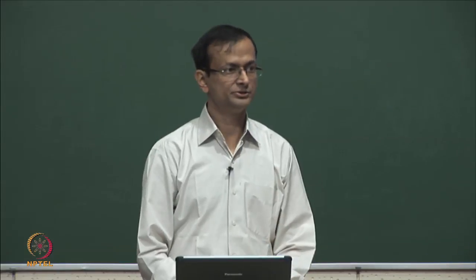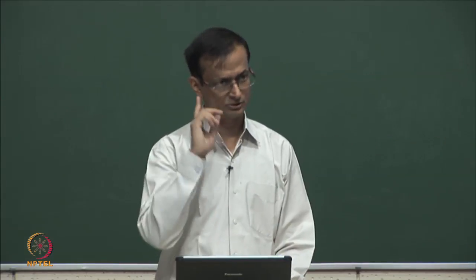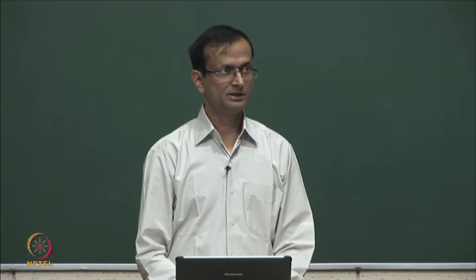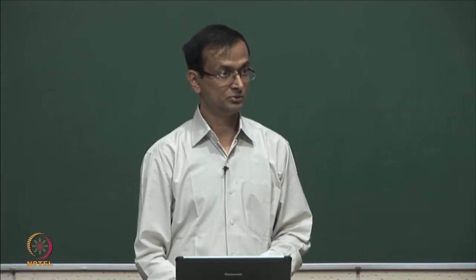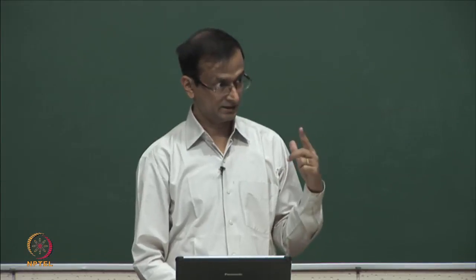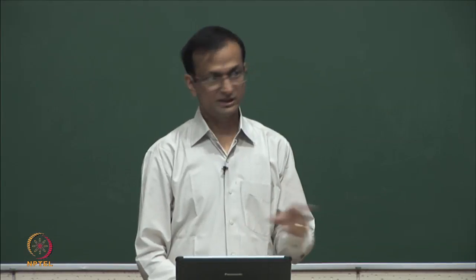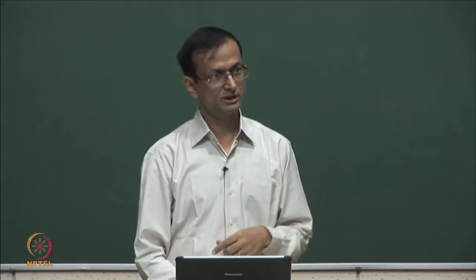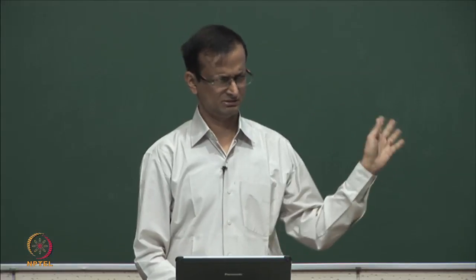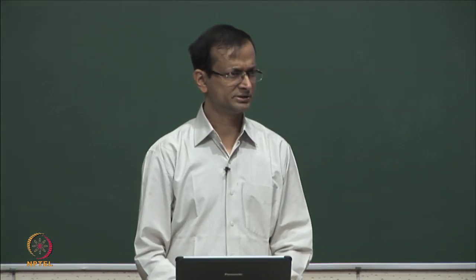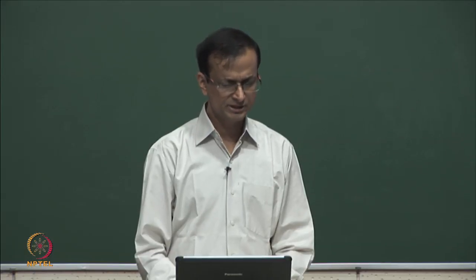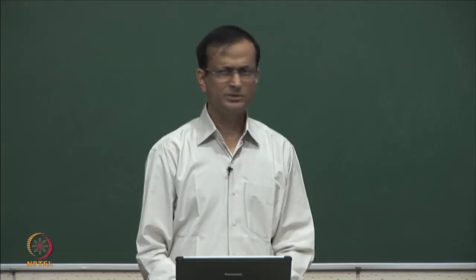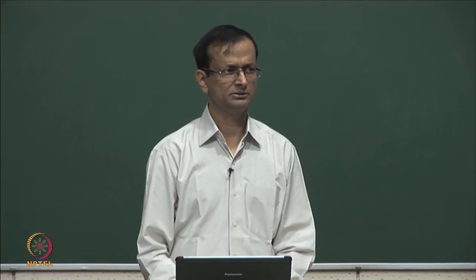Here they are LUTs, but remember the way we were doing the tech map, there is a series of steps where first we did a decomposition into inverters and NAND gates. And then there was a mapping of that structure, and there was a particular matching and covering strategy that we had. What would the equivalent here be? First of all, LUTs are library elements, but how do I go about the matching?